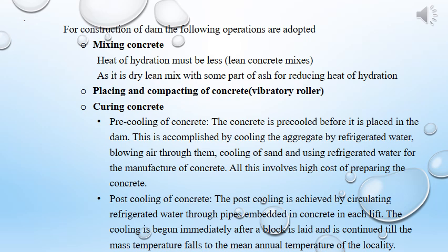After the mixing of the concrete, comes the placing of the concrete and compacting of the concrete. Here some vibratory roller is used, and then comes the curing of the concrete. Here the curing is in two stages. The first is pre-cooling and the other is post-cooling.